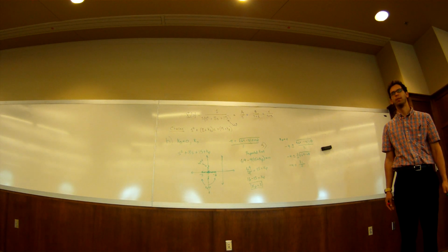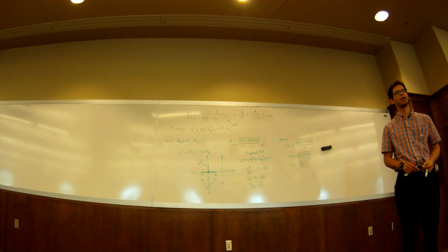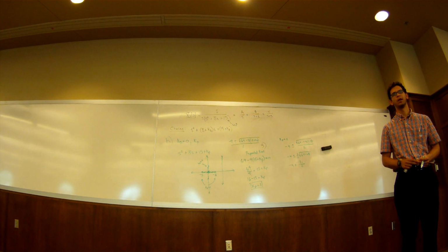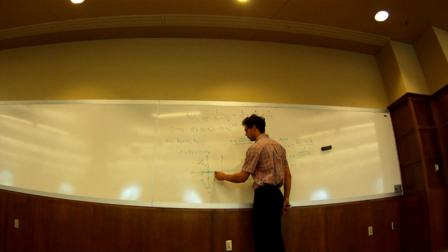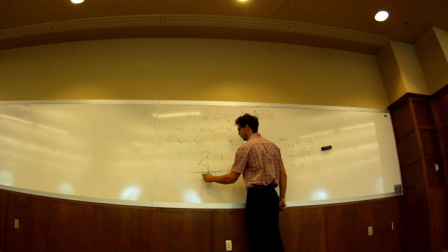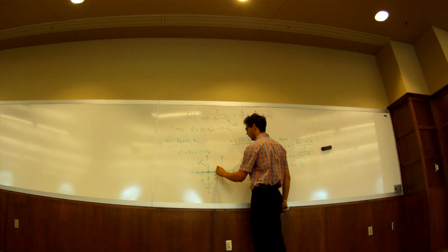Make Kp negative. Yeah, but how could you make this system unstable? Oh, no, that's too complicated. Yeah, you can make Kp negative. If you make Kp negative, your poles would do this, and then sooner or later you would cross. So this is Kp less than 0.